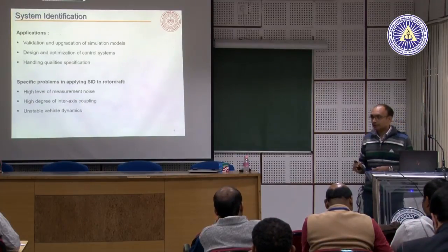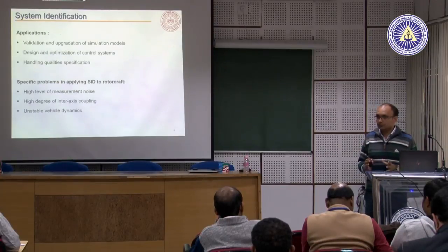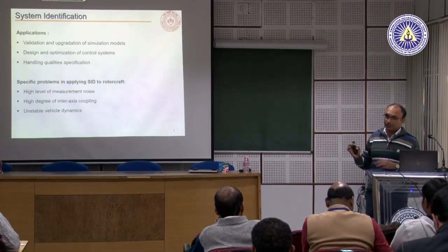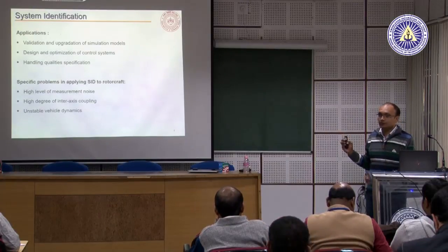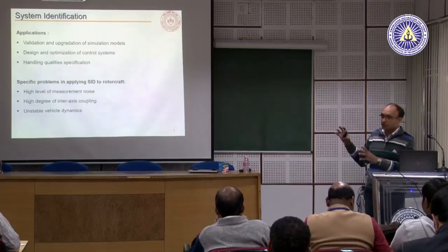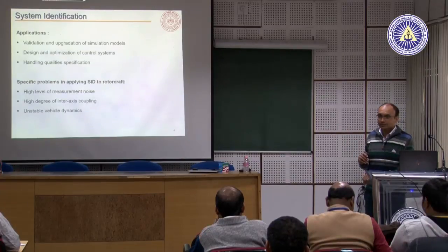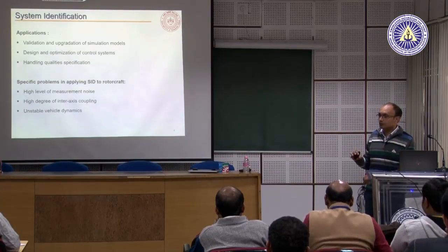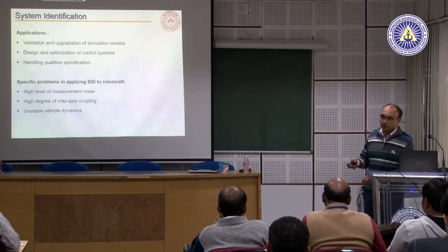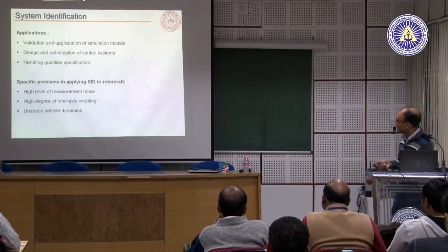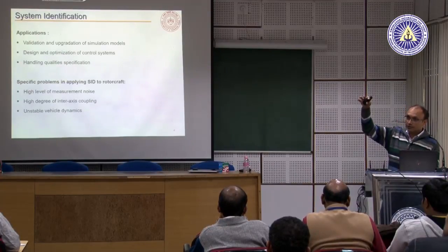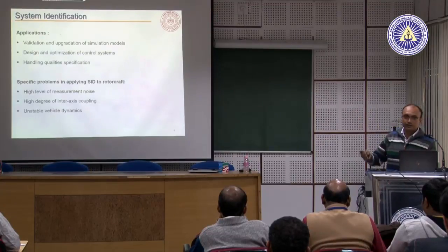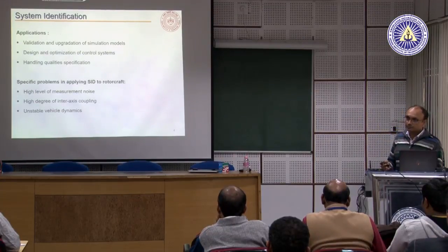And the vehicle itself. We did not go into the stability aspect of the helicopter, but we did derive the linearized equations. We also mentioned that if we do eigenvalue analysis of the linearized A matrix which we got, we would know the eigenvalues, which correspond to the natural frequency of the helicopter system. If we had done that, you would have learned that even though a helicopter is designed and made primarily for vertical takeoff and landing and hovering flight, it is actually highly unstable in hover.